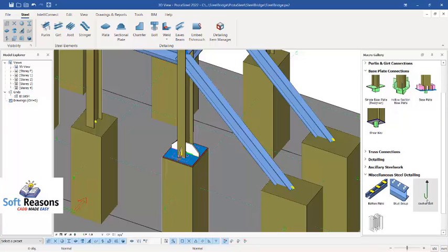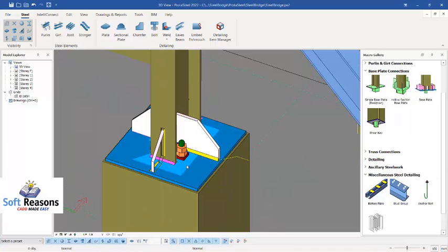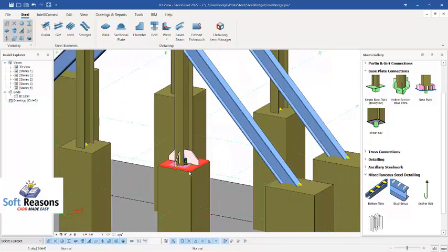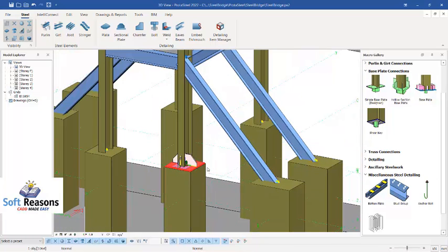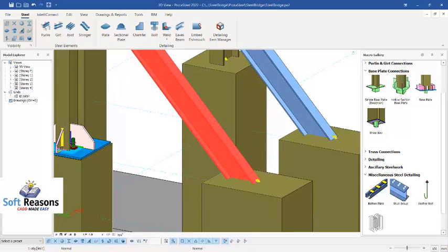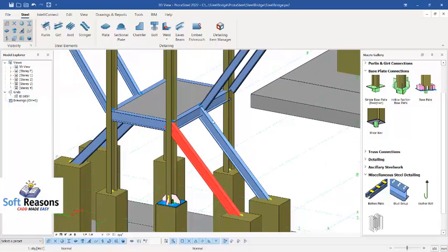After which you just have to get to the miscellaneous, where you have the anchor bolt. So just click once, right click, then select the plate to have the anchor bolt in place, as you can see. So this is what is going to happen to this other base plate and the rest of the pedestals, so as to connect the stations successfully to the pedestal. But for this one, it is going to be manual. All right, we'll manually model this successfully.